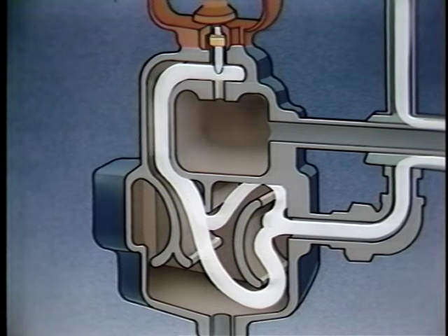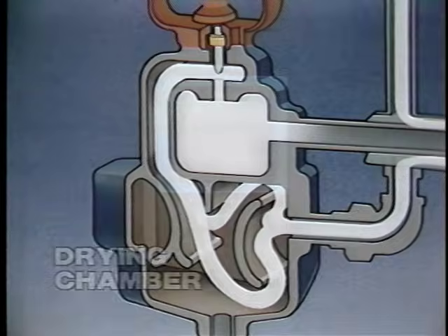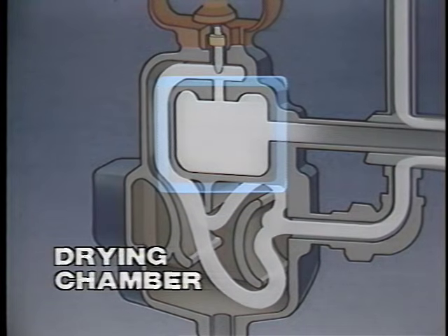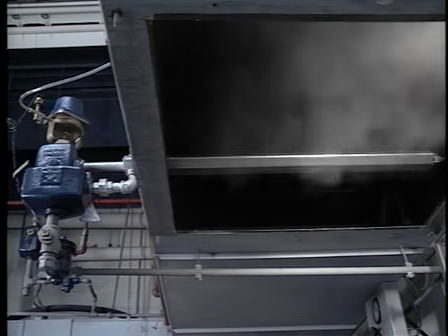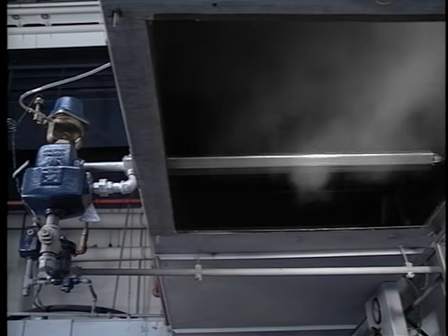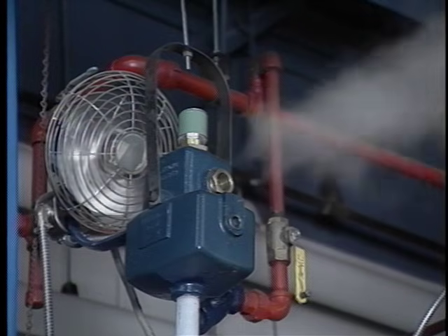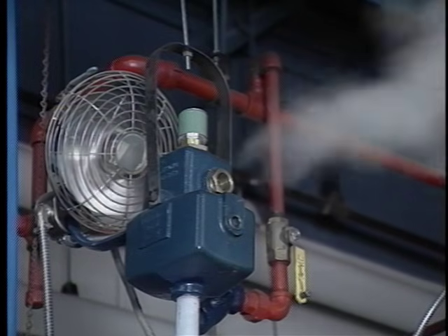After passing through the metering valve, the steam enters a drying chamber that is also jacketed by steam from the separator. Any mist remaining in the steam is re-evaporated here before distribution. This allows the 9000 to be used for either duct or area distribution without concern about spitting.